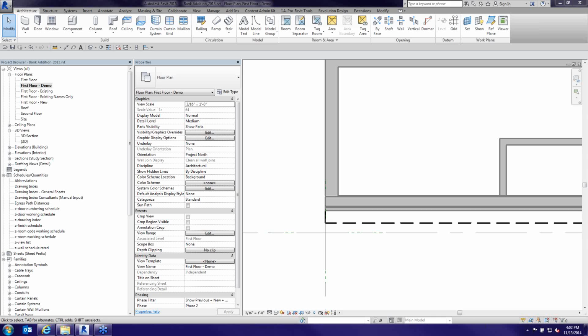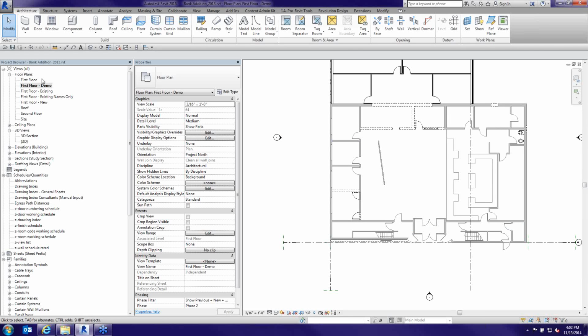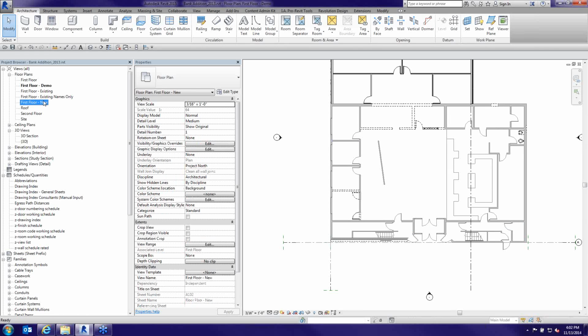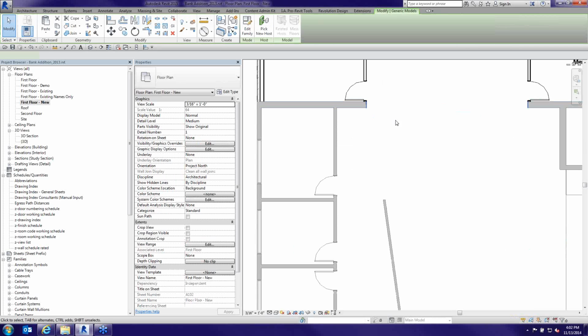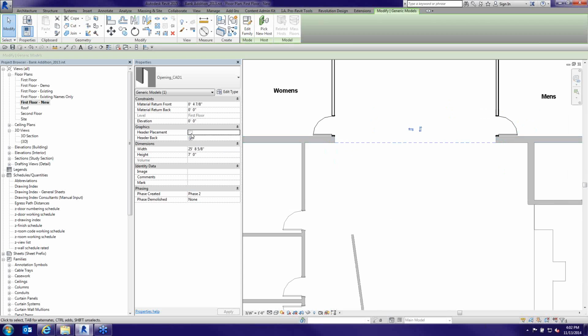New tenant? Rick asked, is the opening family I use different than the opening family out of the box? Out of the box opening family actually gives you casing, which I think is crazy. And then my family, so it's a little bit different, actually gives me the capability to add like a header line on either side of it as well. So a lot of times I want to show there's a bulkhead above, I can show it, or if it's truly like a gypsum, like drywall opening, I like to be able to see it.